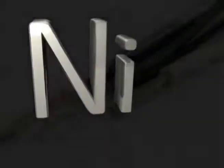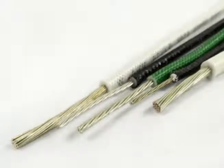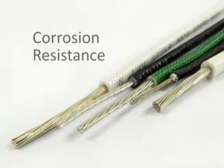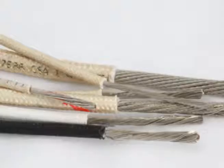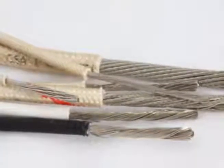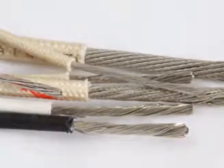Nickel-plated wire also operates in extreme conditions and over a wide temperature range. If the nickel plating is thick, it can withstand temperatures up to 750 degrees Celsius. Nickel also adds a layer of excellent corrosion resistance. High-strength alloys are other materials commonly used as conductors. These are typically silver-plated or nickel-plated as well.